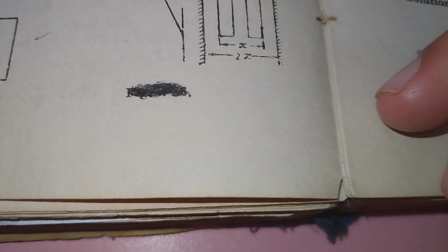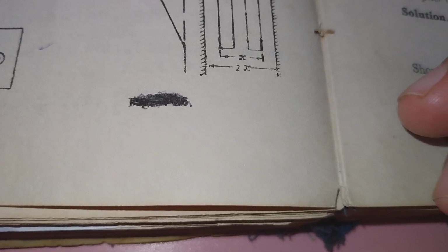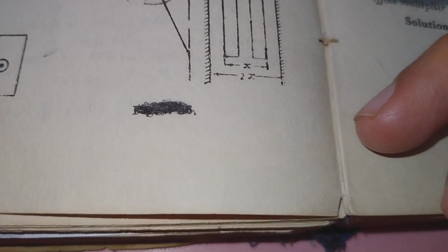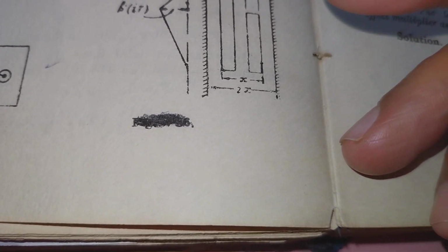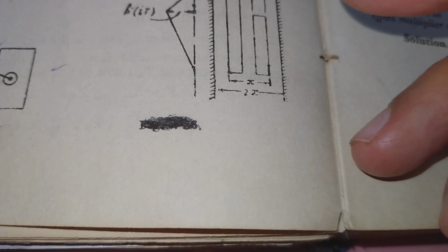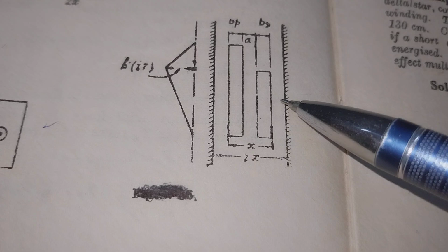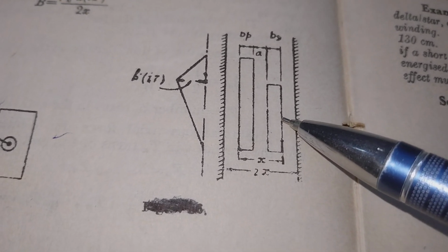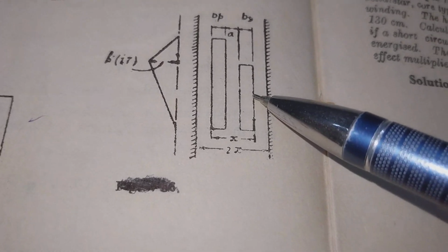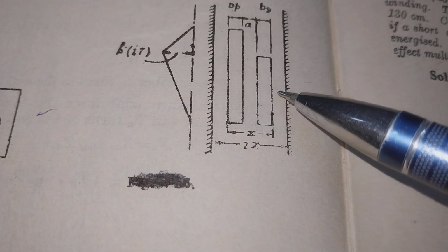The outer unbalanced MMF produces a radial field which in turn interacts with current in the winding producing axial force. This axial force may develop to a quantity sufficient to lead the transformer to failure.